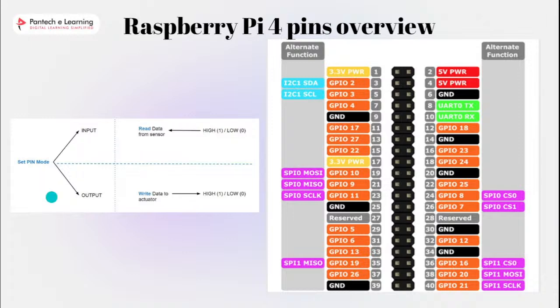And then coming to these 2 pins, mentioned as reserved, which are 27 and 28. So pin 27 and pin 28 are reserved pins. They are usually used for I2C communication with EEPROM. I hope you know about the topic EEPROM. So if you just begin with Raspberry Pi 4 pins, don't connect anything to those pins. There are many other available pins for you to use. So that's 14 slots already taken for ground, power supply and reserved pins.